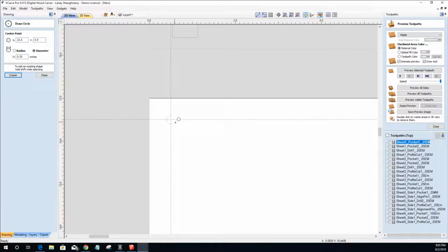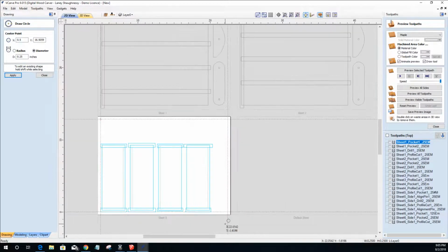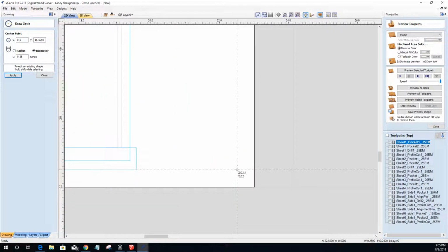I got these guides created so I can just go right to them each time, and they're pretty much exact. If I set myself up exactly right, I could make sure that on that first cut, my X and Y, all of my sheets land in the same exact spot every single time, and my 0 is on the bottom left corner in that same spot.